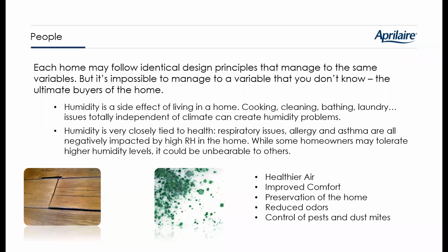And Joseph, are you going to talk about kind of what the zone is that you want to keep that house in later on? I will. There's actually a slide I should have put in here that I did not, that has the ASHRAE chart. Maybe we can include that in the recording, where the zone is. And the reason I'm glad you brought that up is there's a high and a low zone for it, right? So we want to be roughly between 30 and 60, probably closer to between 40 and 50, honestly, around the 50% mark. And in some climates, that would require managing both times of the year, adding at one point and removing at another. So very important that both sides of that zone are considered.